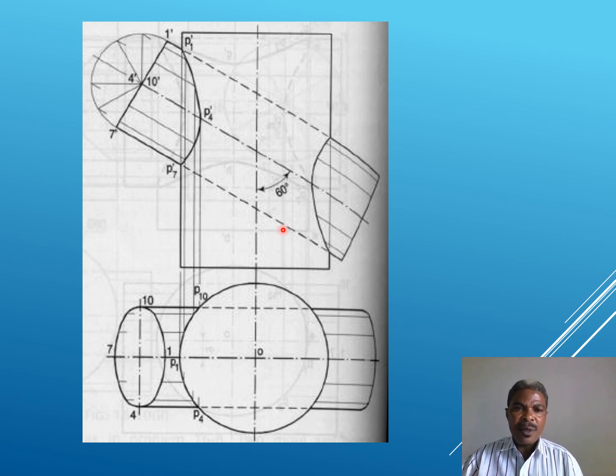Another example is provided here, whereby the angle of interpenetration is given, measured from the vertical axis of the standing cylinder, as you can see. How to get the curve follows the same procedures. You have to draw a semicircle very close to the base of the cylinder that is interpenetrating. Note that the points and numbers laid here will change position when laid for the plan view, as explained for the previous cases.